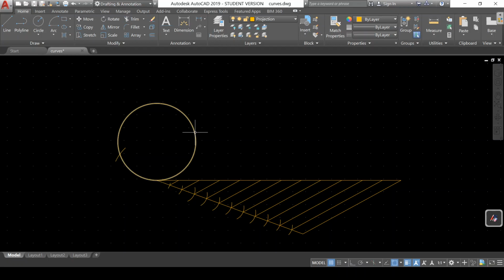Now we have to divide this circle with respect to this P. Don't divide this with respect to this contact point, which we did for the first sum. That was the case because the contact point was the point P. But in this sum, this point P is 35 mm away from the contact point. So we have got the point P here. With respect to this point P, we have to divide this circle into 12 parts. So let us do that now.